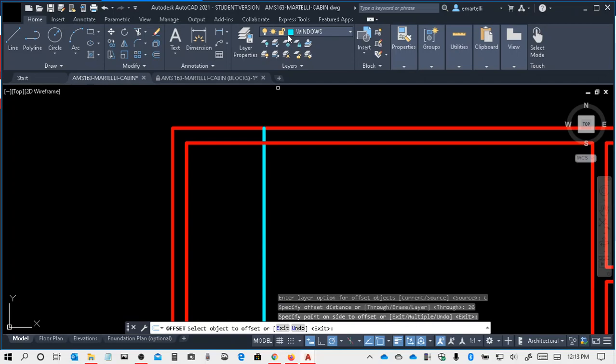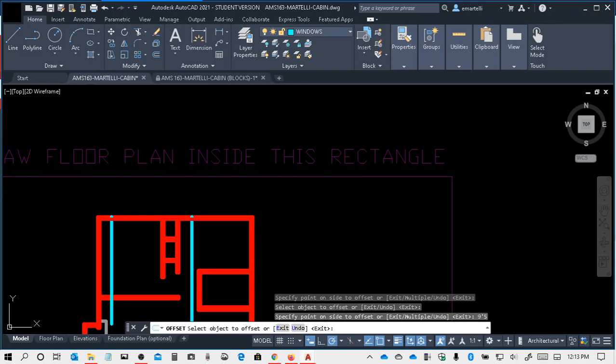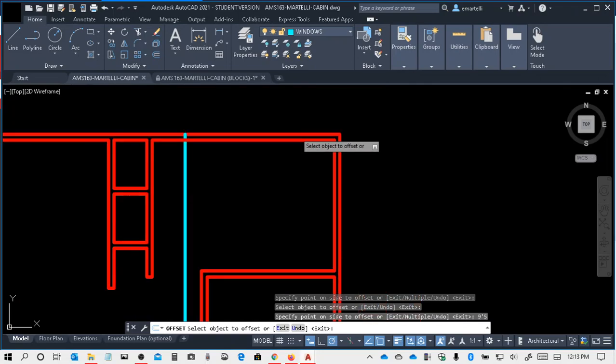Okay, we got some more. Let's see, there's a 3040 on the opposite side. So I'm still in select mode for offset command. I pick the outside here, and I come across, looks like 9'5", 9'5", enter. Okay, so that's going to be for that window. Okay, it looks like they picked the outside of this rear exterior wall and come towards the front, 6 foot even, 72 inch. And then they take that line and come forward 4'9".